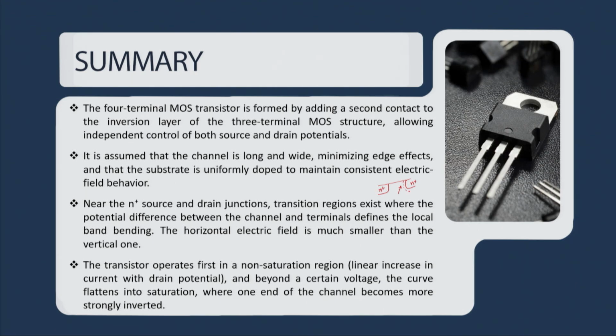To avoid this transition, we assume that there is no expansion of the depletion region in N plus. Further, we assume that we are only interested in drain to source current and consider ideal effects, like an ideal gate oxide and ideal depletion charge, and hence we considered the gate current and body current to be 0.